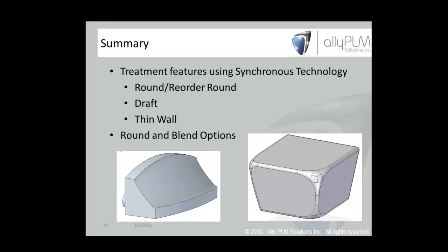And then we looked at round and blend options. Some of those you may have used, some of those you may not have used. We looked at the softened corner for the round, being able to do a setback value or a value like 1.5 times the radius value for the setback for the soft corners. We also looked at the blend options, the different options for that, and how we can actually blend faces. The big thing when rounding, think, how big of a radius is and what's my available real estate. So a lot of times when you see your round failed, you made a change above it in the tree, think, well, is it that move that obviously means the round will not fit in that spot? And then you can come back and maybe use some of the tools that you saw today to fix those. Maybe it's a variable radius round to give it a little bit more control in a certain spot, or maybe even doing a blend.